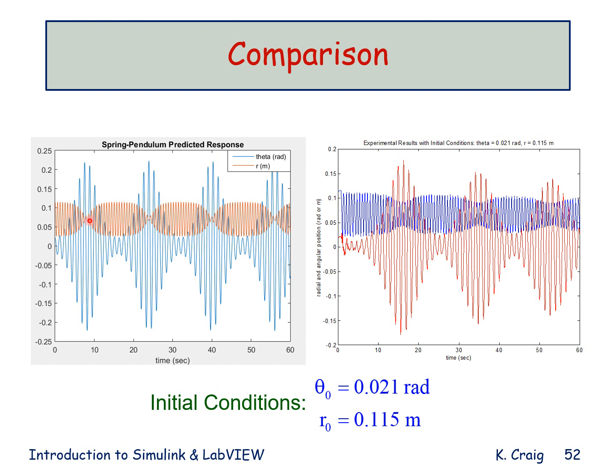It's very distinct in terms of going from one mode of motion to another. Here, not as distinct. I still get the theta motion even when the R is at a maximum. Theta doesn't completely go to 0. I also see there is decay in the amplitude because of friction, and in my simulation, since I have not modeled friction, I don't see any decay.